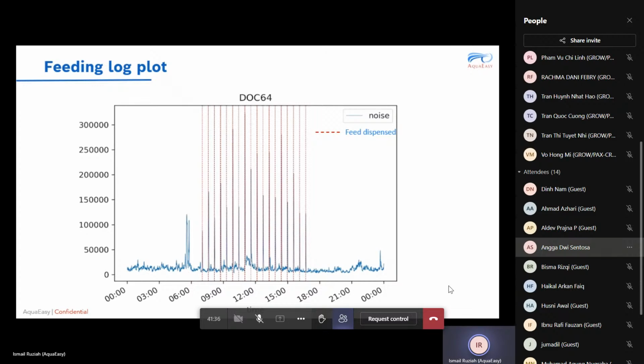The next important thing is that iFeeder will not add boosting or skip feeding unrestrictedly. We set some limitations or regulations to control the boosting and the skip feeding. Stephen has introduced the feeding table, so we know the planned daily feeding amount for the day. Then the maximum boost feeding amount can be configured at roughly 20% of the daily feeding, or 10% or 30%. This percentage can be configured. Based on our experience, we roughly set it at 20%. This value can also be changed based on the farmer's preference.